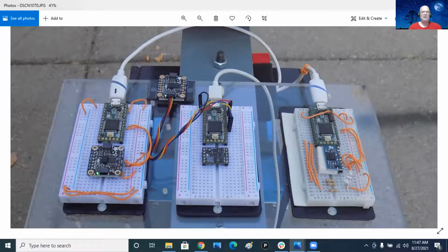Now I gave up on that one because once I get it on the vehicle, I can load the values in, but as soon as I start driving around, the calibration level starts dropping. And I finally decided that since I can run it without loading any calibration data into it, just turn it on and drive around the block, and it's tracking almost as close as my GPS heading, if I don't touch it, that seems to be working fairly well. But I can't get the BNO085s to do anything like I want them to do.